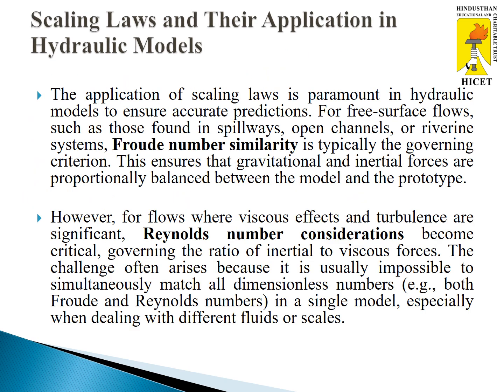The scaling laws and their application in hydraulic models. The application of scaling laws is paramount in hydraulic models for free surface flow such as those found in spillways, open channels or riverine systems. Froude number similarity is a typical governing criterion. However, for flows where viscous effects and turbulence are significant, Reynolds number considerations become critical, governing the ratio of inertial to viscous force. The challenge often arises because it is usually impossible to simultaneously match all dimensionless numbers, for example both Froude and Reynolds number in a single model, especially when dealing with different fluids or scales.